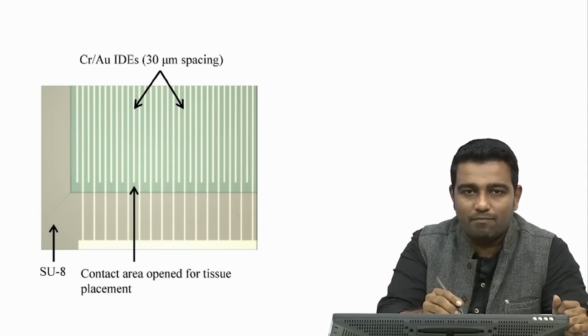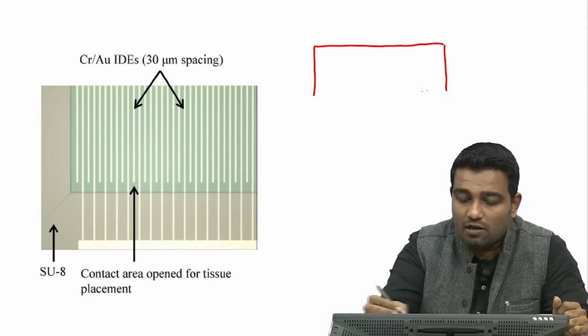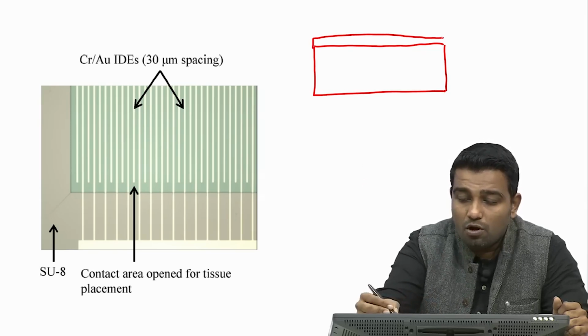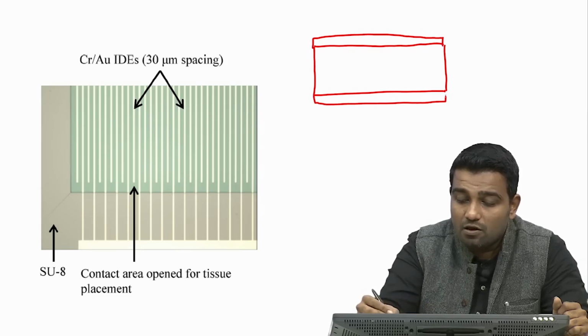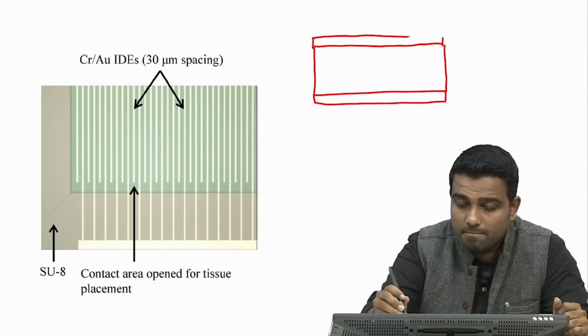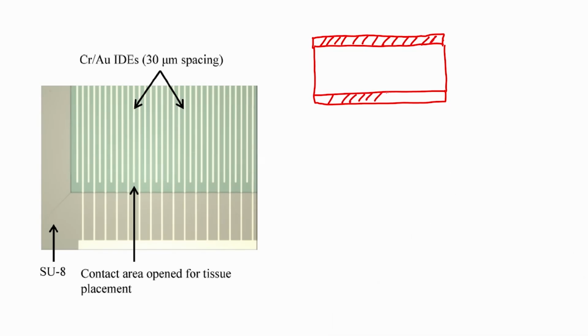So, if you take this particular example which is on your screen, the first step that we performed is we took a silicon wafer, and then we have grown oxide using thermal oxidation, and this was done at 1200 degree centigrade using wet oxidation technique or dry oxidation technique. Until this we have seen.